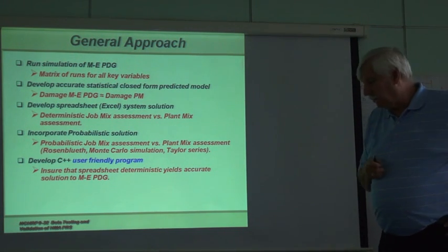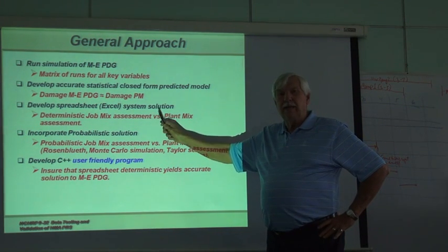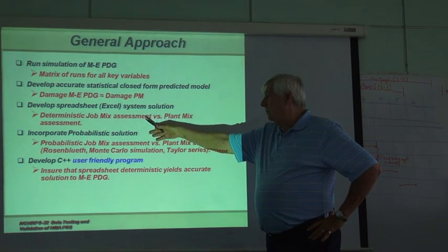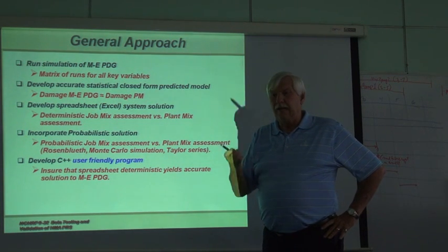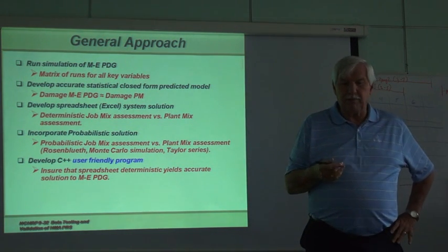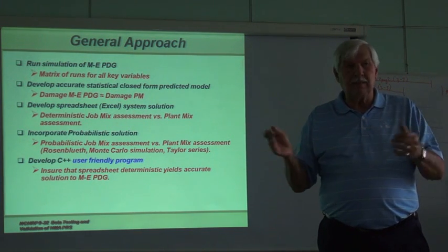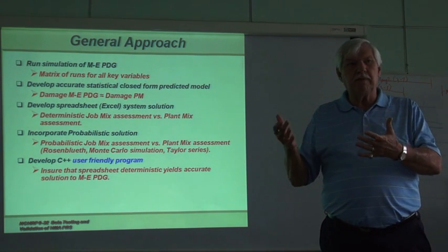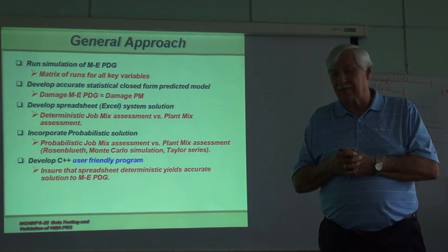What we have to incorporate is differences between what the contractor places and the variation that he may have in doing that. Okay, what we have here then is to start incorporating probabilistic procedures. I don't know in your approach for specifications if you have what we call PWL or percent within limits, or probabilistic. In other words, you sample 10 times and you see what percentage is within limits. Well, that's the very first cursory step when we get into probabilistic analysis.